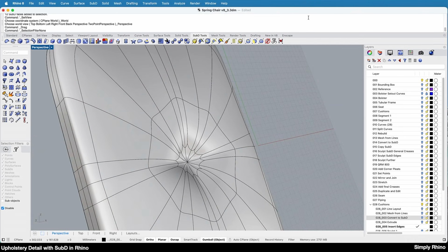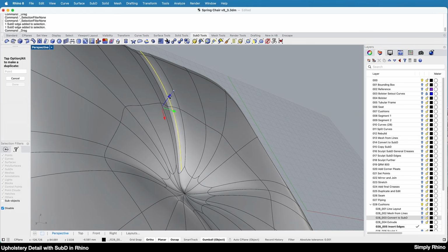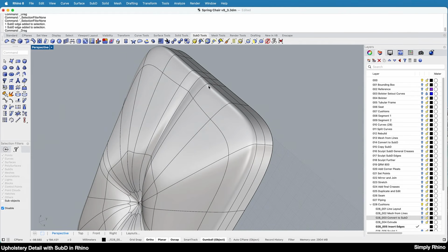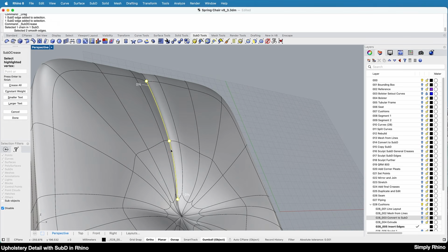Now I can start to make the creases or pleats that are created by the button pulling the upholstery inwards. I'll look at just one crease to start off with. And first of all, I'll clear the face selection here and then pick these two edges before moving them in slightly. I could then choose to either carry the crease over the edge or wash it out smoothly before the edge. I could also sharpen the recess by adding a soft crease. So, if I pick these two edges here and then add a 60% or even 80% crease, this will add more definition without changing the topology.